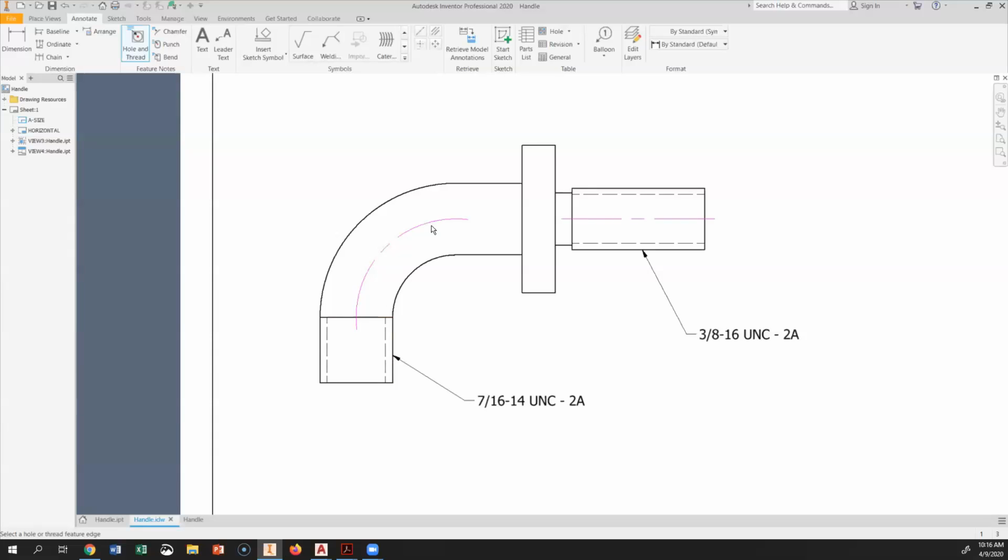What I have done also, showing this format here, is to have a center line for this first. And then don't need to have this too long. If you want to reduce a little bit, you can. And then add in this dimension, make sure that you pick this option without, you don't use this one or this one.